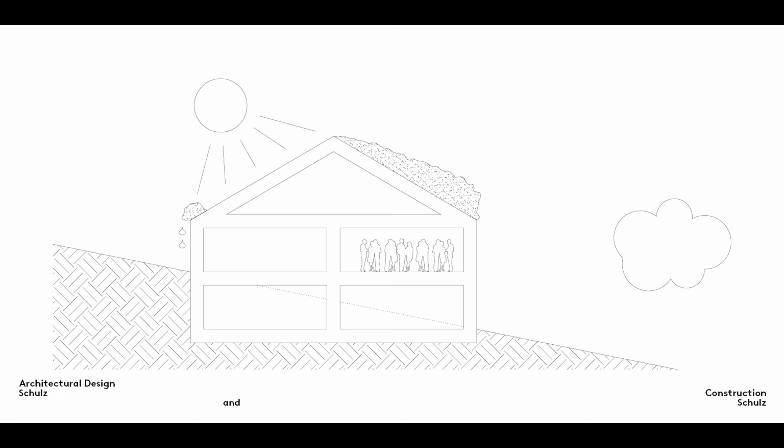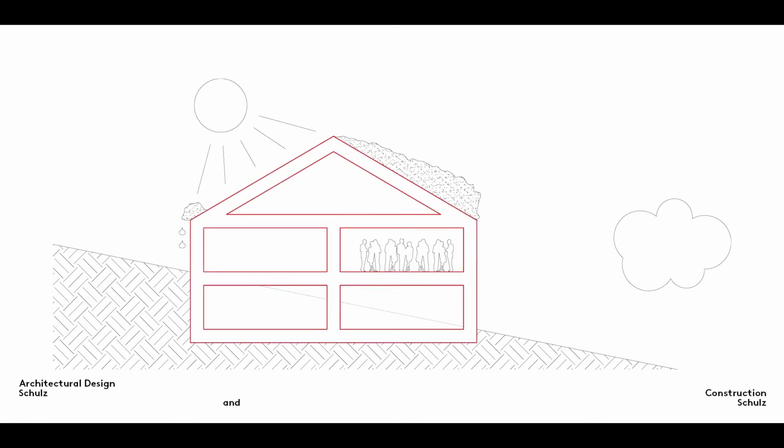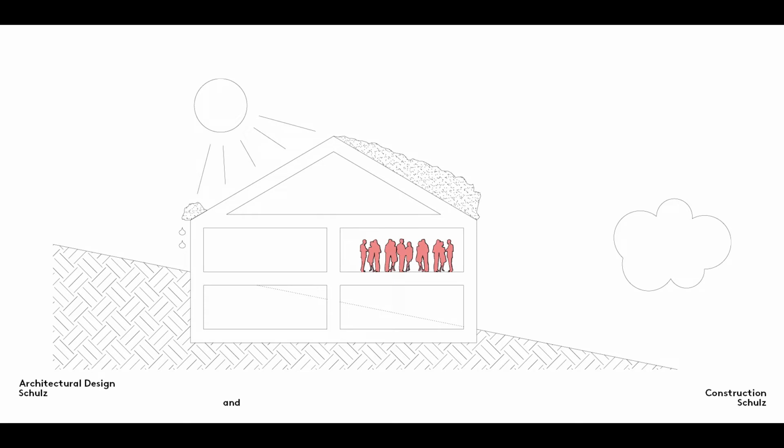The duration category is divided into dead or permanent loads and live or variable loads. Dead loads refer to a structure's self-weight and are constant over time. Live loads are temporary and result largely from the building's use, including the people and furniture in it, for example. These are known as traffic loads. Other live loads may be caused by environmental factors, including the effect of snow and wind, earth pressure, or dynamic phenomena such as vibrations, for example.